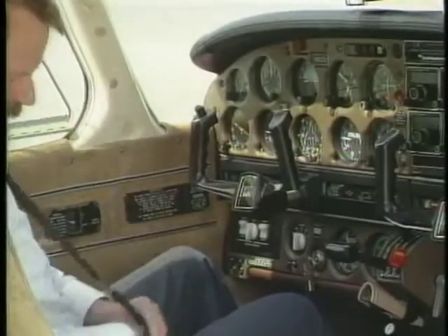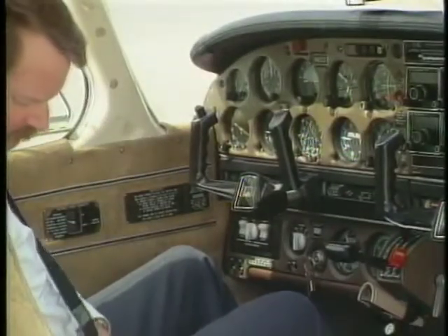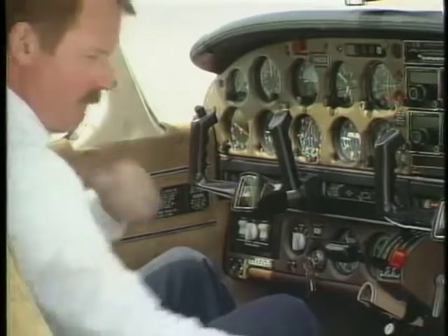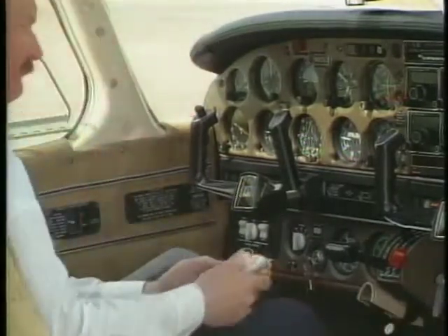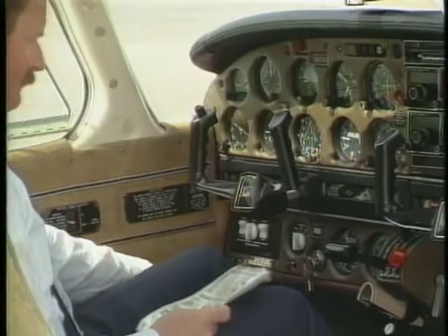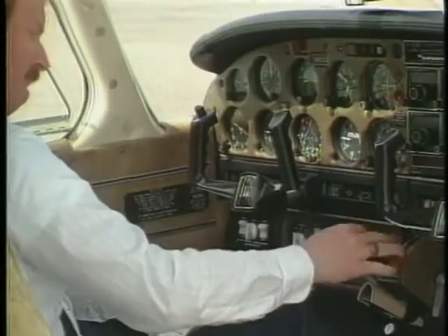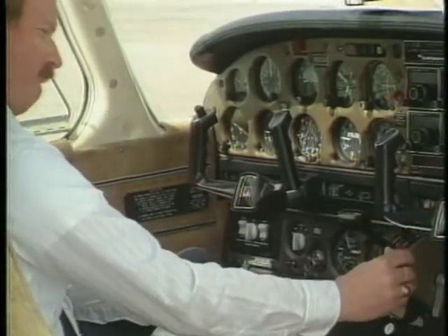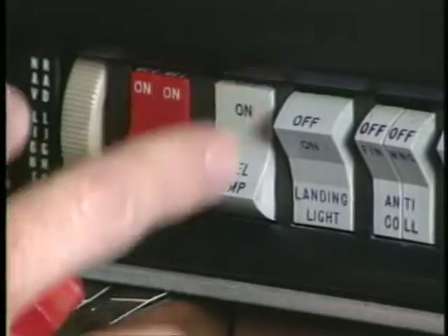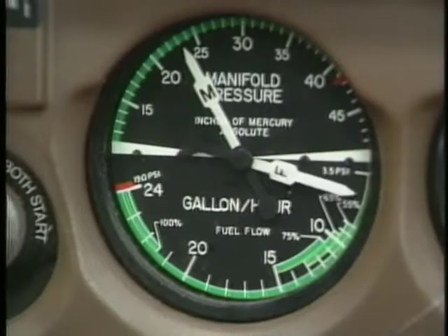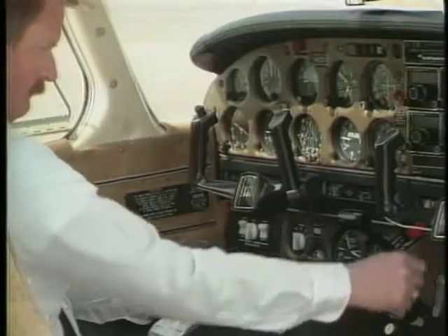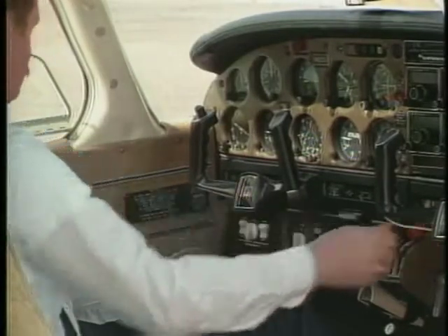The last topic we'll discuss is starting procedures. Although the starting procedures vary between manufacturers of fuel-injected engines, all of them have one thing in common. That is, if the engine is cool to the touch or is being started for the first flight of the day, the system will have to be primed. This is accomplished with the auxiliary fuel pump. With the throttle and mixture set according to the POH, turn on the electric fuel pump and monitor the fuel flow indicator. When a sufficient fuel flow rate is noted, continue with the specified starting procedures.